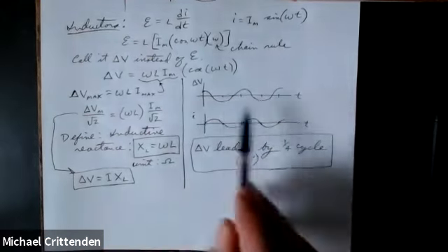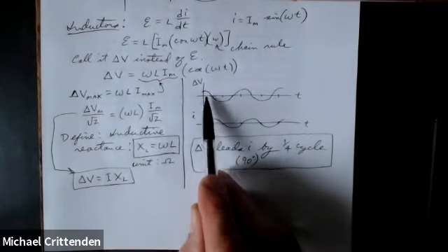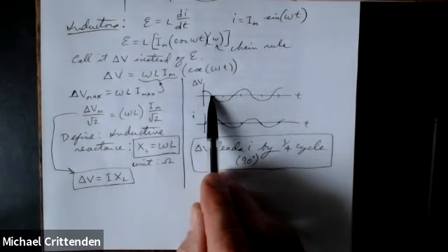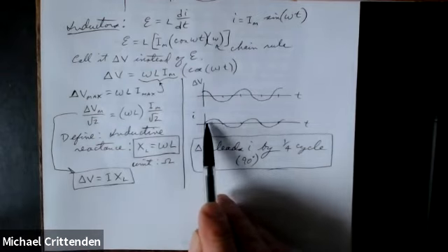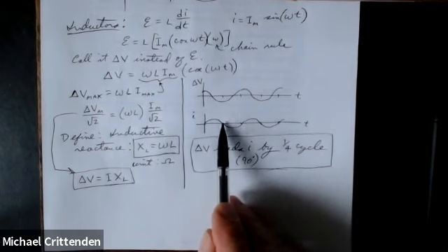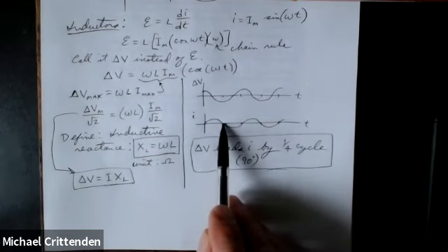Or at any other point along the graph, like right here, where the voltage goes down through 0, the voltage does that 1/4 of a cycle into the picture. The current goes down through 0 half a cycle from the origin. Again, voltage did it first, current did it later. So voltage leads, current lags.